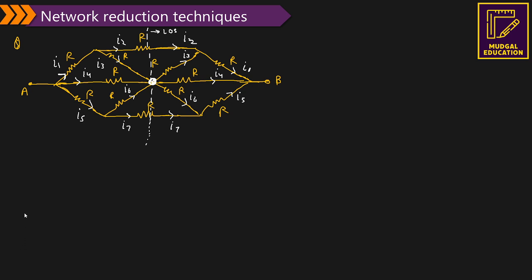Now see very carefully. The current I3, see the laser pen. The I3 is going in this direction and going towards the upward direction. It comes out below and goes towards up. Again, I6 is coming towards here and going towards below. Then I4 is going straight. It means that the node here is actually a false node, because no current is going to cross this particular node. So we have a false node here.